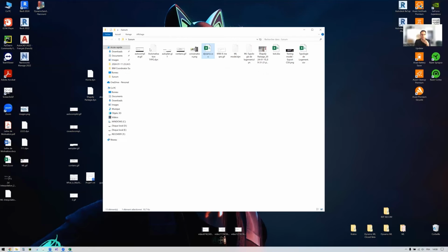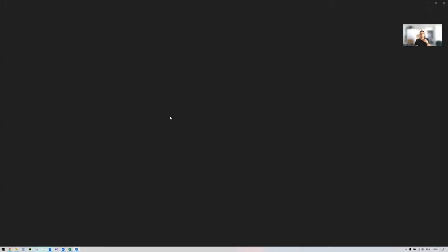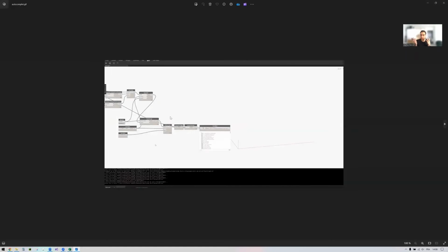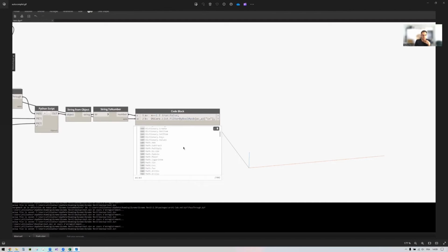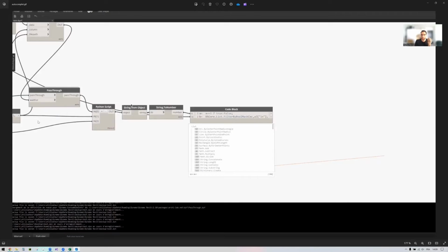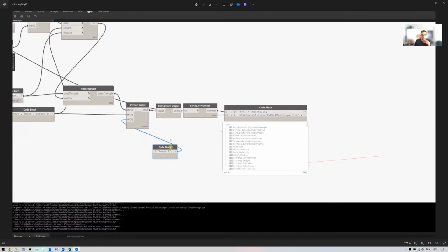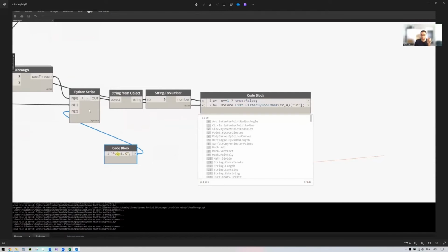If you look, you may notice the formation of this data is actually an autocomplete mechanism. What do I mean? Here comes the CSV file, the CSV file we looked at a little earlier in Dynamo. Its node names representing the inputs and outputs, and also an example node name coming from the input. So here, if I enter point X, it means that this loop can potentially use all other nodes as a result.